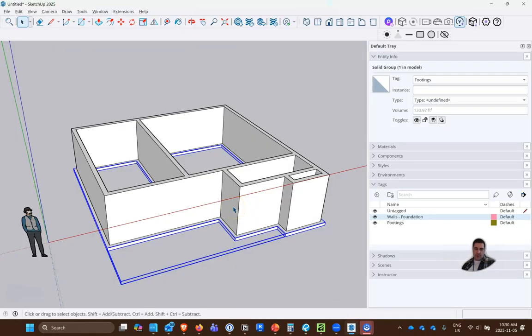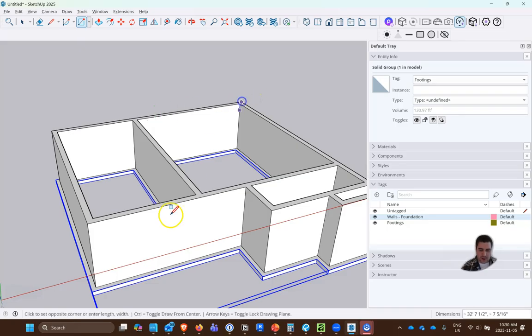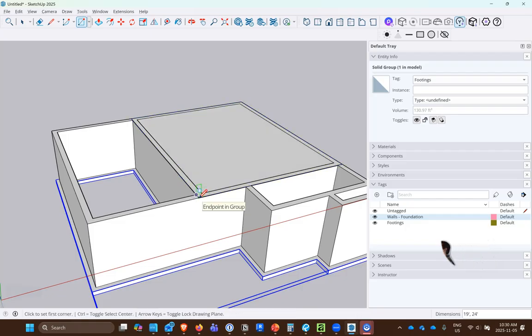And probably the more complicated part of that piece is our 2x10s are not actually 2x10s. Do we all know that? Everyone? Some people? Okay. So the 2x10s are what's called a nominal size. Typically lumber will start off as a 2x10 and get milled down to its finished size, which in our case in Ontario and Canada is 1.5 by 9 1/4. So our floor height is 9 1/4.